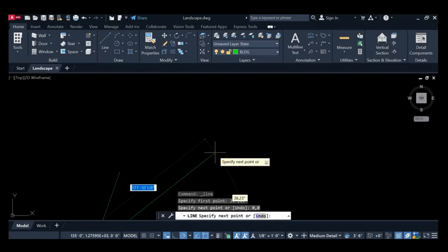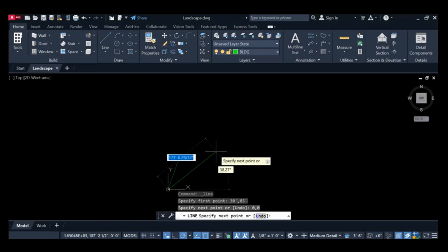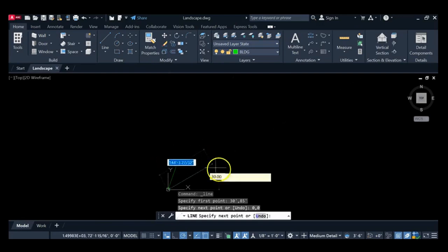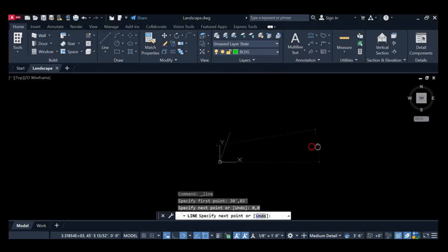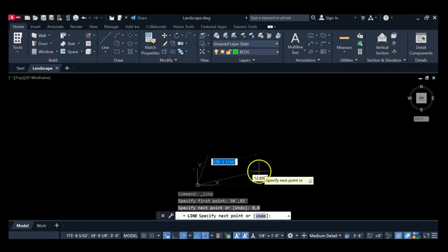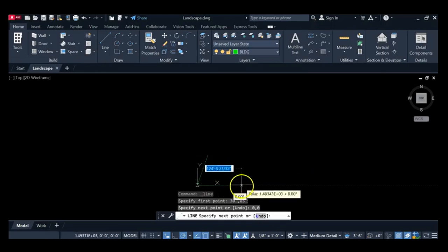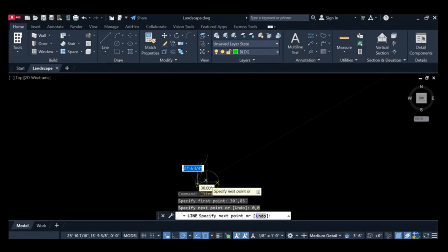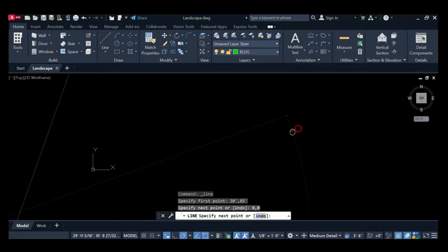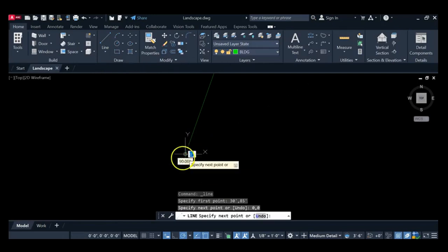we're going to zoom out by simply using the wheel on our wheel mouse and dragging. I am going to press and hold on the wheel, and a little hand comes up to pan. I'm still pressing and holding on the wheel. If I move the cursor without clicking anywhere closer to the 0 and zoom towards the screen by rolling the wheel, that's my 0,0.